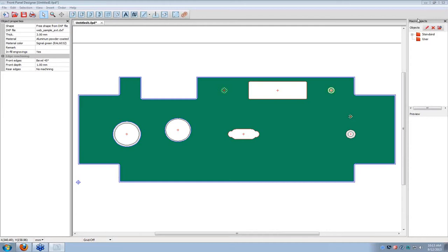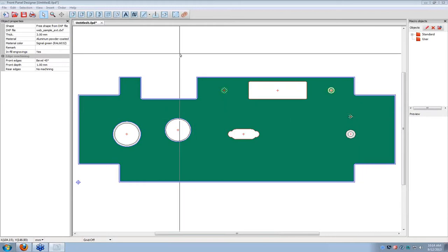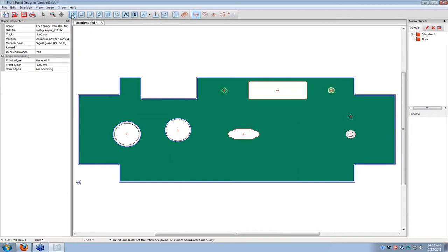So one common question we did get is about a keyhole and how to create that object. There's one of two ways to do that. You can either stack two objects, a circle and a square, to get that keyhole effect, or you can design it and save it as a DXF file. So that is probably the way that we've most seen it, is creating it in another AutoCAD-based program and then saving it as a DXF.